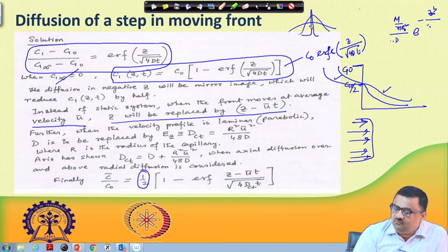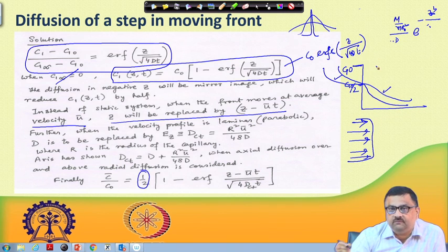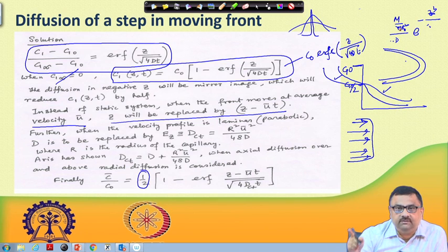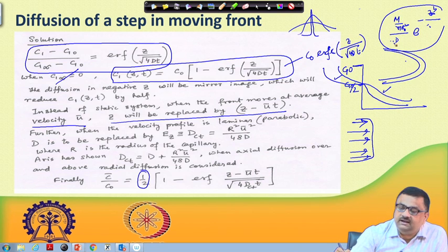Now, on the other hand, when this Dirac function is placed in a capillary where a non-uniform velocity profile was set in by virtue of the laminar velocity profile, where this pulse is stretched in the form of a parabolic distribution, in that case also, you remember, if you look at the final result of Taylor dispersion, we stuck to that same form of equation, m by A divided by some term involving pi Dt, and then e to the power minus z square divided by some term involving Dt, etc. So, this same form we maintained, only instead of D we had here Ez.